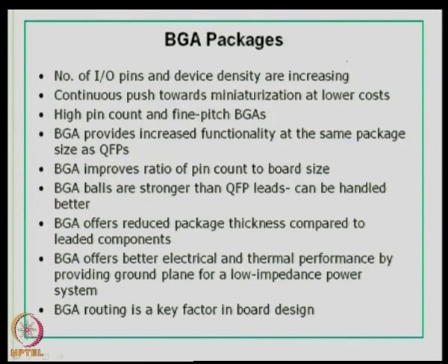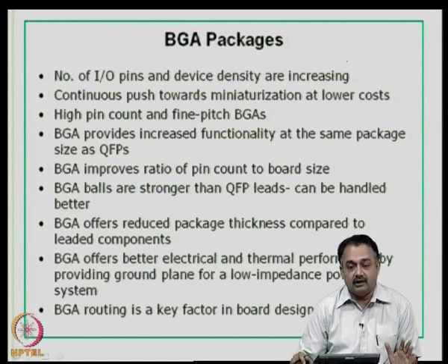So, a BGA package today is a workhorse of the industry, and we will finally look at the summary of BGA packages. In a BGA package, the number of IO pins and device density are increasing. Today, you can get BGA packages of the order of 1100 pins or more. So, how to handle them?